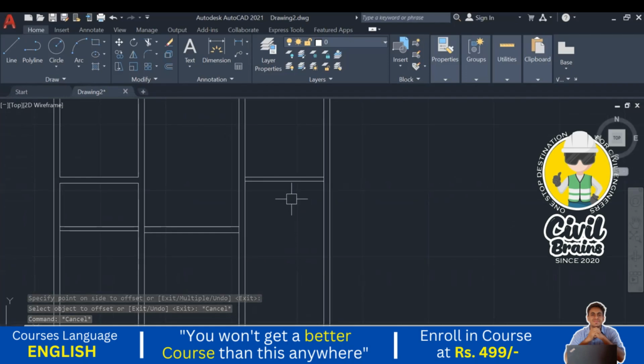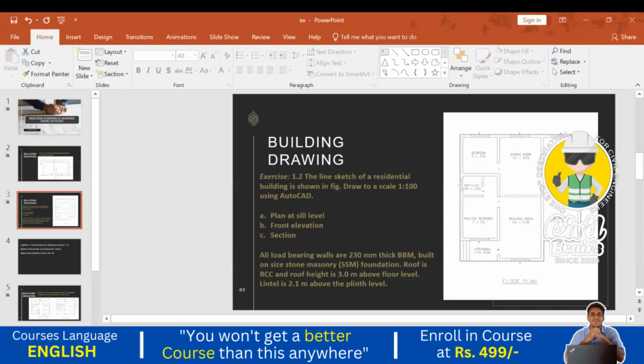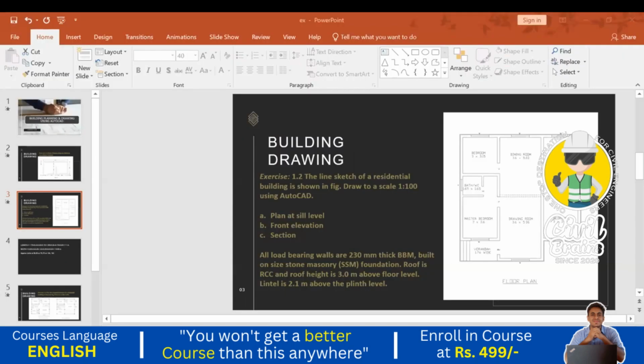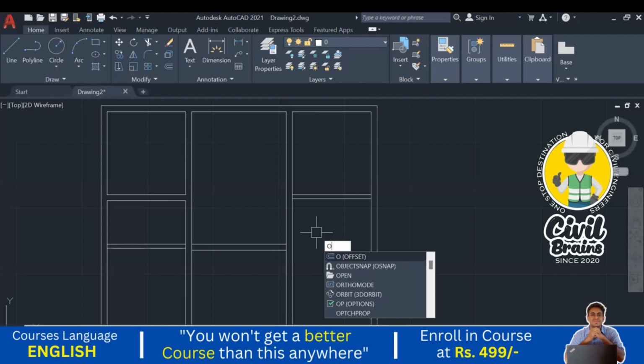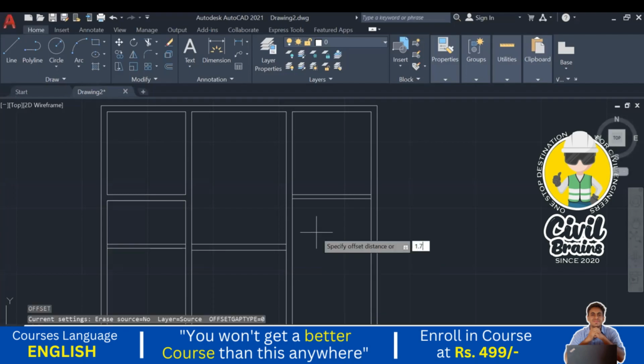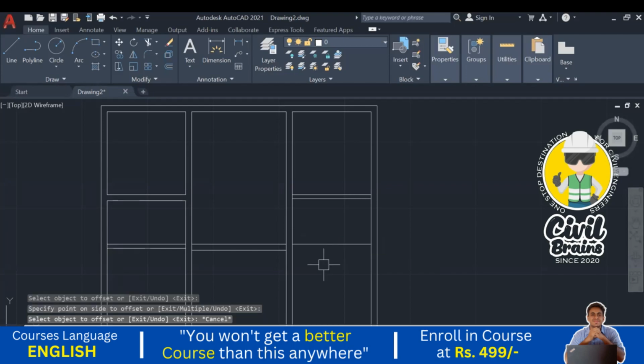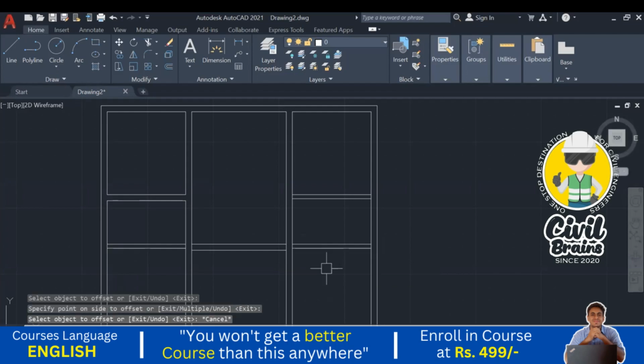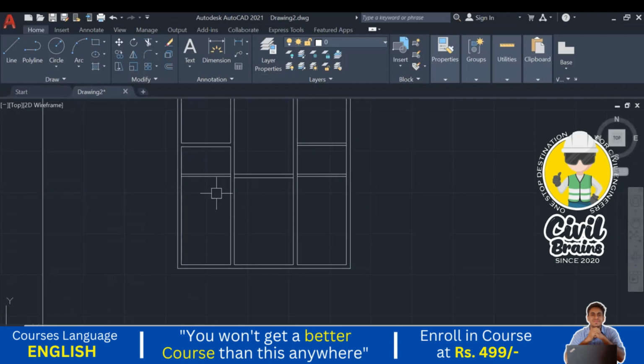So next, this one. Here, what is the dimension? So here there are no rooms. Here it is 1.73 and the partition wall. I just come here. Offset 1.73. Press enter. Offset 0.15. Enter. Okay, so openings, after drawing the walls, then we can go for the openings. Now we are not bothered about the openings and how to draw the doors and all. We just complete this one first.